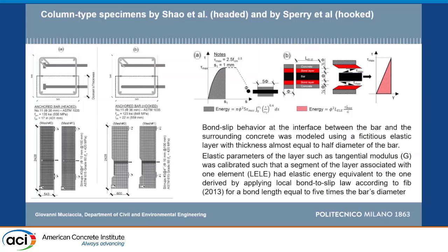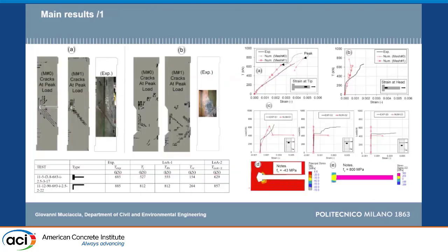So we modeled bond as a uniform bond layer, intermediate to the bar, which has the same energy in shear, which comes from a bar which could slip and has this behavior which you already know. So this is an equivalence. Again, because the focus is not on steel, the focus is not on unbonding, we want, of course, to have the displacement associated to that, the load transfer, but not unbonding. Okay, so we kept this hypothesis.